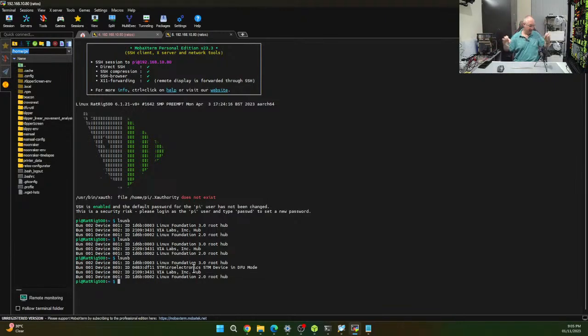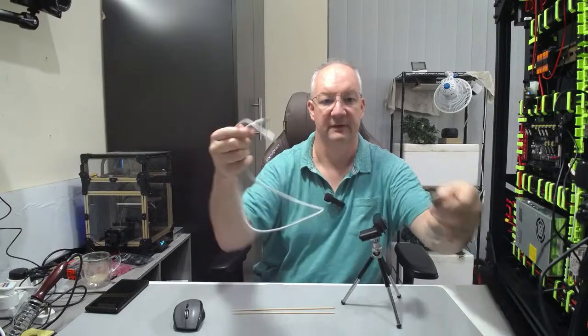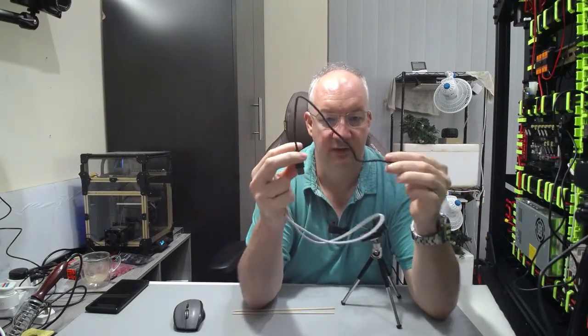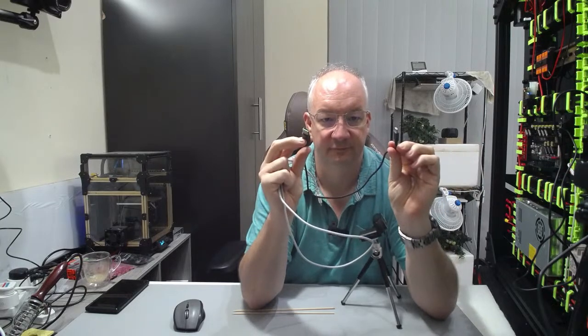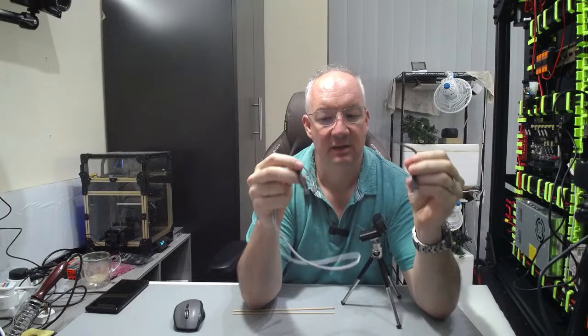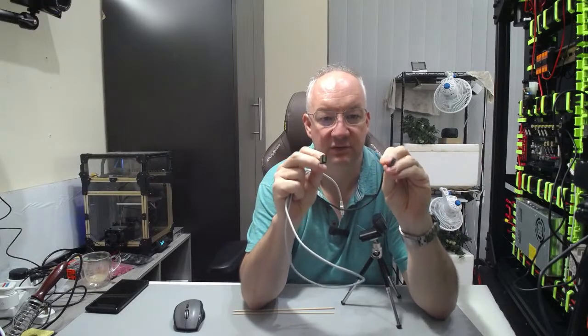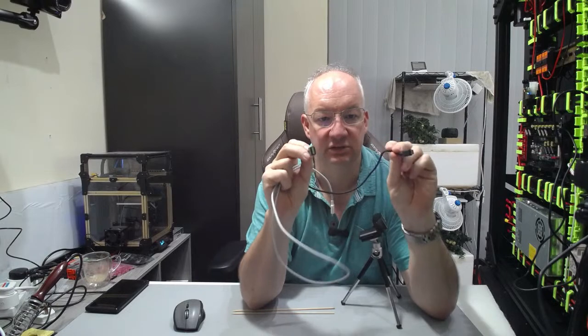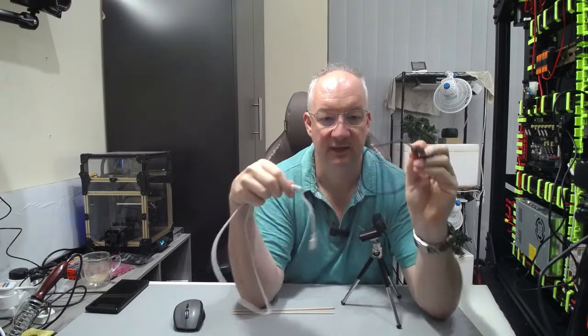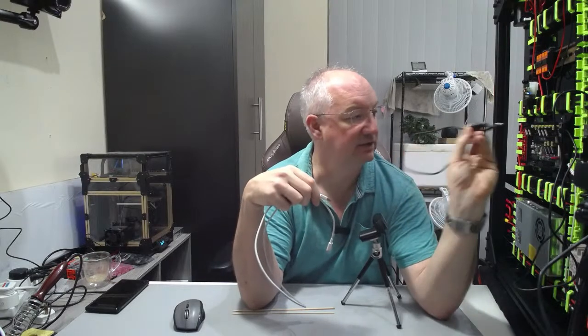Okay. So let's come back to this, right? I grabbed a short cable and I thought it was going to be working fine, right? But when I tested, I didn't test with this cable. Not all USB-C cables are data cables. Some of them are only charging cables, right? So it only pushes power with no data. And that's why this cable will not actually connect to that board.